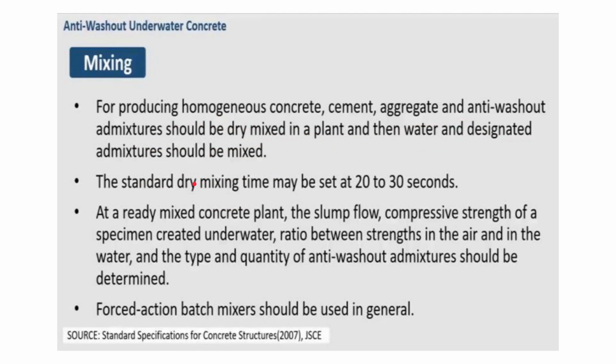Okay, the standard dry mixing time may be set at 20 to 30 seconds, just as we saw, 30 seconds of mixing dry, and then after adding water, 1 minute. At a ready mix concrete plant, the slump flow, compressive strength of a specimen created underwater, ratio between strengths in the air and in the water, and the type and quantity of anti-washout admixtures should be determined. Forced action batch mixers should be used in general. So these are some of the rules to be followed.